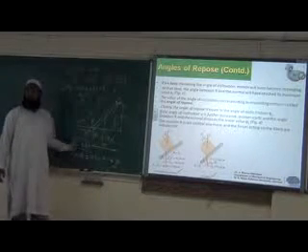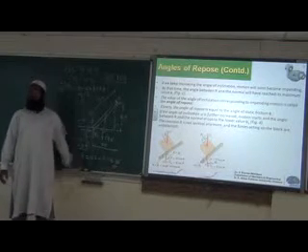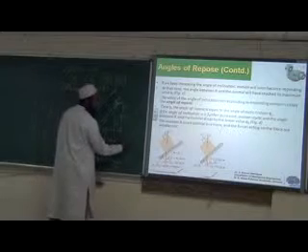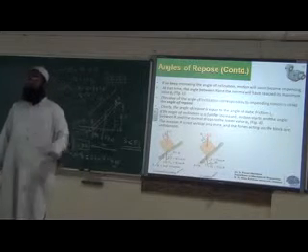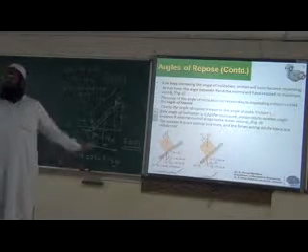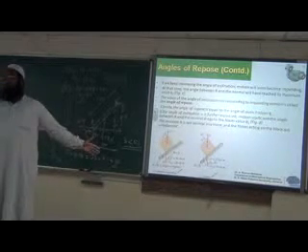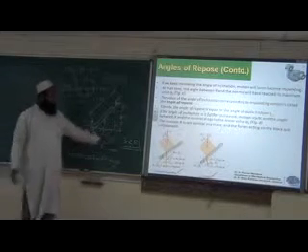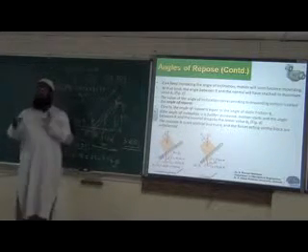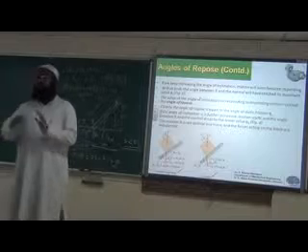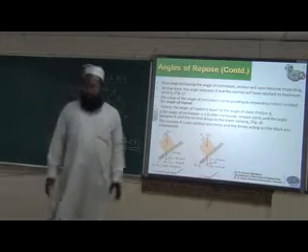Okay. So for equilibrium we need only 3, which is already less than 5.1. So 3 is less than 5.1, so we can say this is in equilibrium. It won't slip. For the given friction coefficient, the maximum friction force we can have is 5.1. To keep it in equilibrium, from the given data and load, we need only 3 Newton. So this is within the maximum frictional force we can have, so it will be in equilibrium. It won't slip.